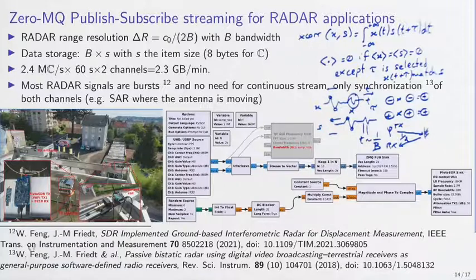And the challenge here is that this motion of the antenna along its rail, first of all, will not benefit from any measurement as the antenna is moving from one step to another, because as the antenna is moving, the signal is unstable, so there is no point in recording this data. Furthermore, we only need to collect a burst of data when the antenna is stable.